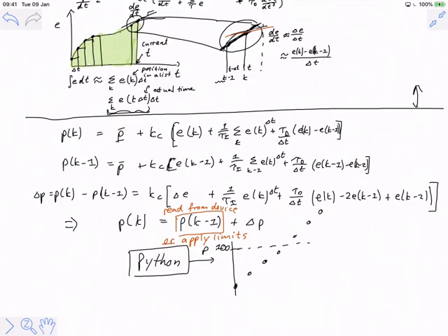So the real difference comes in with, and actually I feel that the textbook words this in a way that is not conducive to optimal understanding of the situation. It basically says velocity mode controllers don't have integral windup, and then it shows you a formula which would exhibit integral windup if you just implemented it as it is in the book.